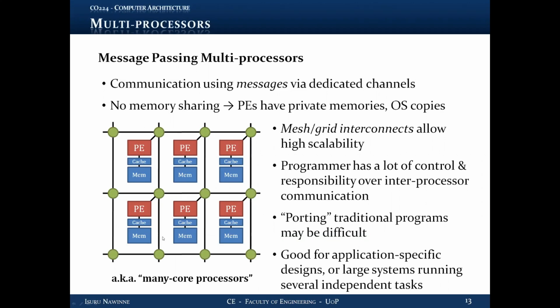It's a network on the chip, on the same chip, right? On the same chip, you have hundreds of nodes containing processing elements, caches, and memories. And these nodes connect to routers, and you have a network of routers connecting to each other. And there needs to be some sort of an addressing mechanism in order for processing elements to send messages to other processing elements.